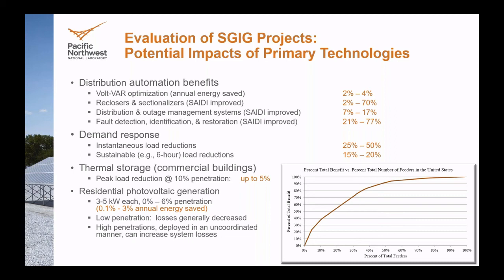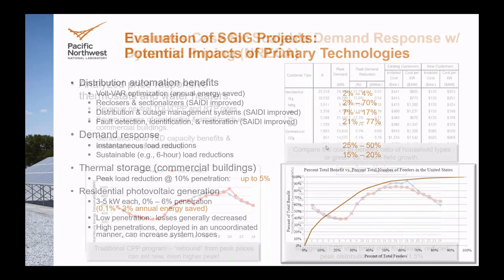And if you're familiar with the Volt-VAR optimization scheme, that makes sense, that certain feeders just are not going to benefit, or they may actually behave poorly with that technology. But being able to apply that to a national scale was very useful, not only for the Department of Energy reporting back to the Office of Management and Budget, but also to utilities, so they could look at this and say, something like Volt-VAR optimization or CVR, maybe we can use this to determine which feeders we want to deploy it on and save ourselves some money. Whereas if we deployed it on all of our feeders, there may not be as much benefit as we expect.